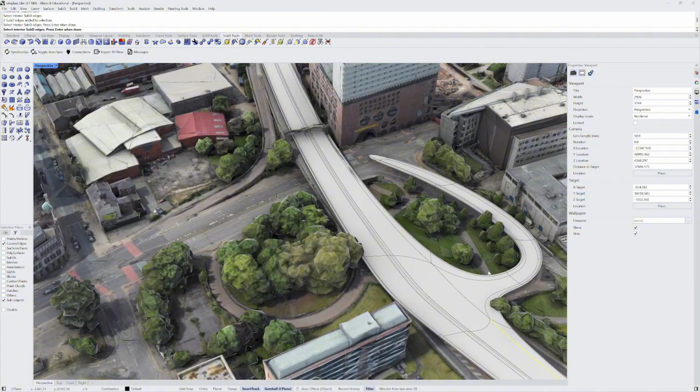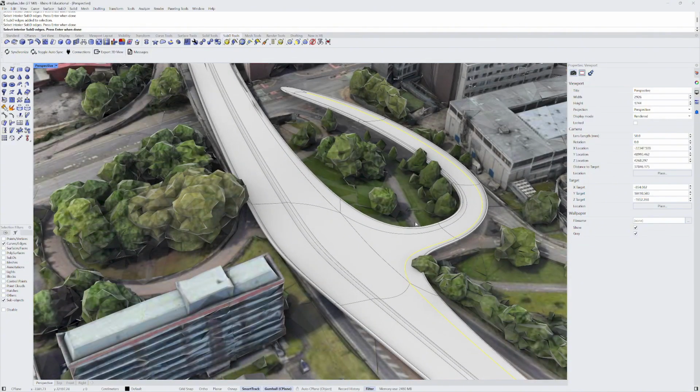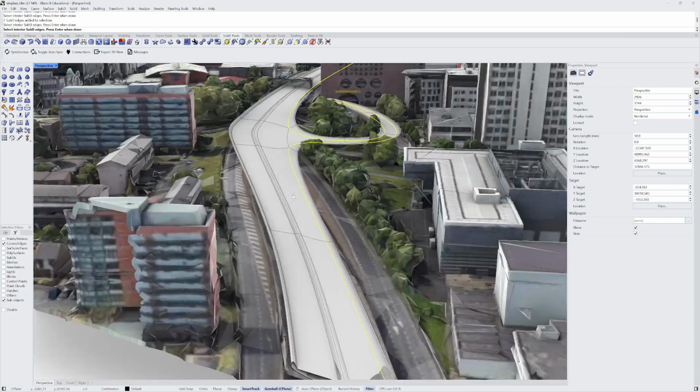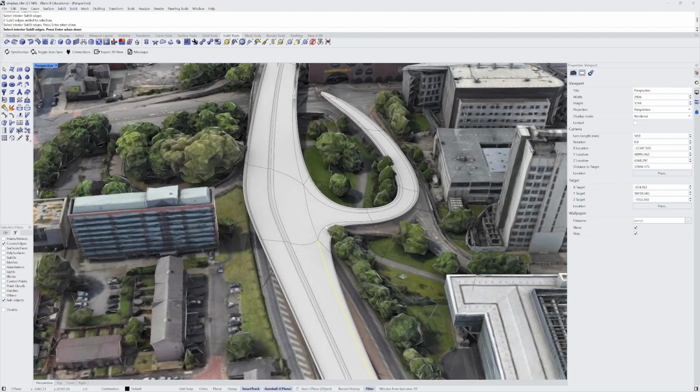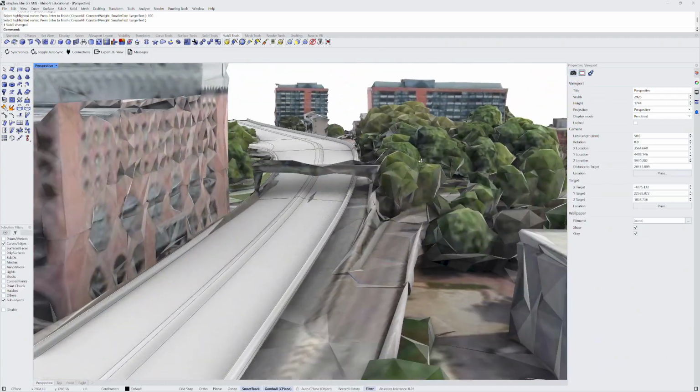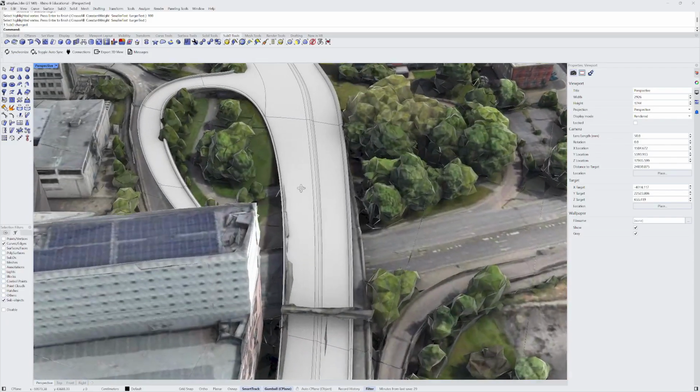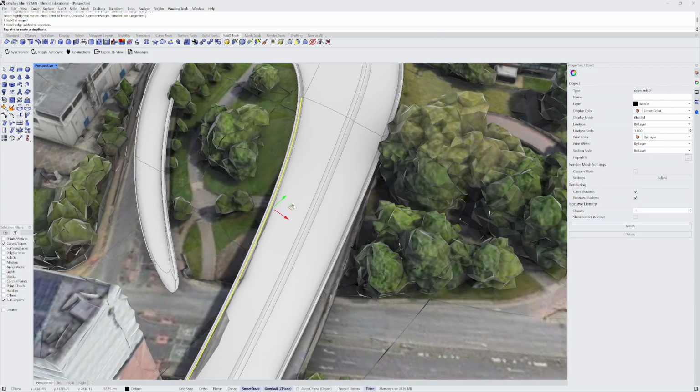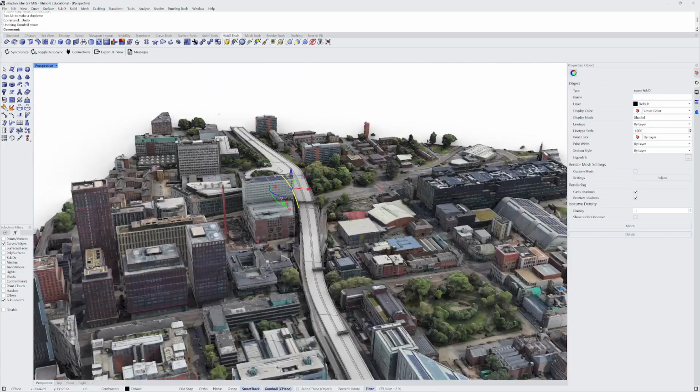And if I get to a point here, I can then select this one, this one, and this one. And again, I can just run the crease command. Do that again, sorry. Press enter, type 100, press enter, and you'll end up with something that looks like that. And the beautiful thing is now we can start to push and pull these faces however we want, and it will start to give us some more geometry.